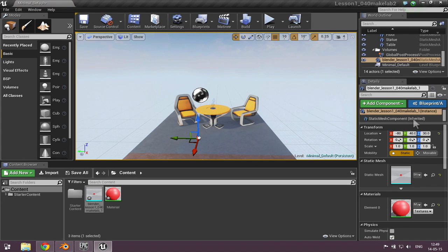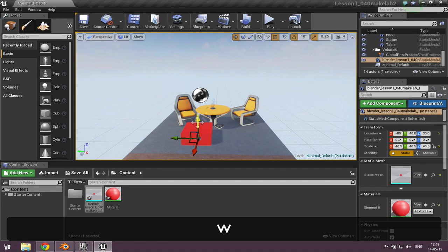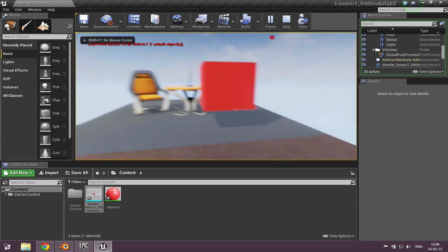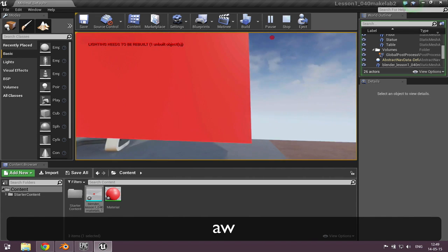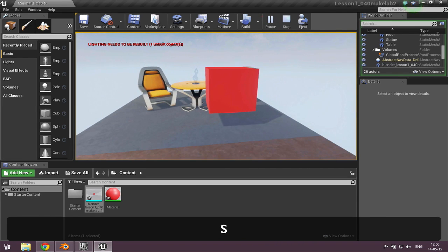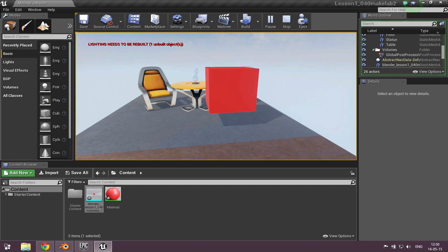It's very small, so I'm going to select and scale. It's the R key, and I can just make it larger. Okay, just press the W key to move it up a bit. And here we have it. We have the same cube inside this game engine, and it automatically got a collider attached to it, so I cannot walk through it. But it shows you how you can easily import these assets built in Blender into Unity or Unreal Engine. Next lesson we'll dive into more detail.